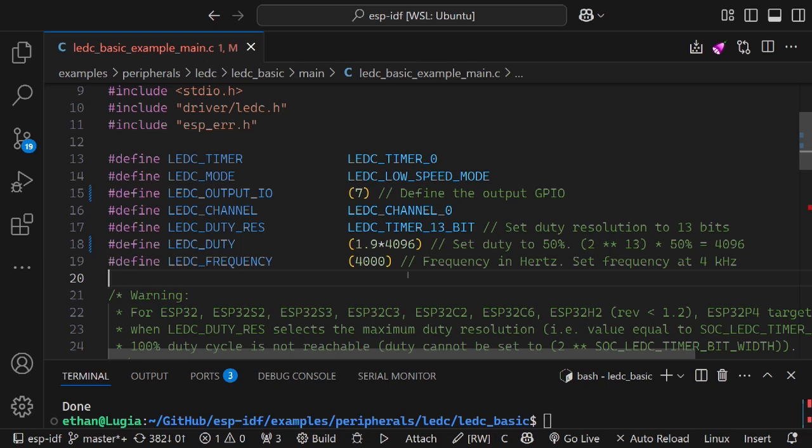A big thing with motor controllers is you want your motor to be running at the optimal speed, in optimal conditions for a very well-known amount of time. If you are running at an undefined voltage because you want it to run a little bit slower, then your motor may have more error in its movement. Versus if you're using a PWM signal, you get a lot more precision in how you move motors.